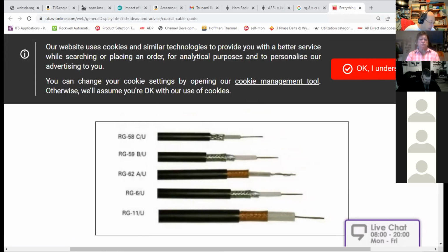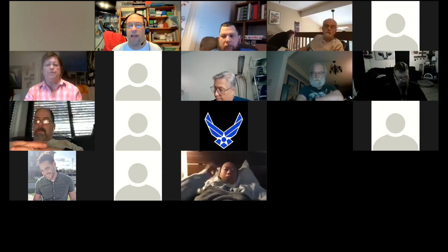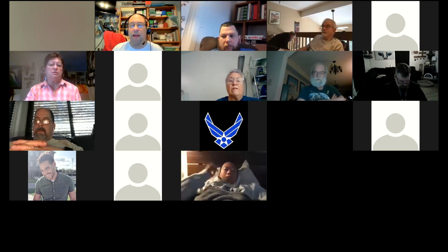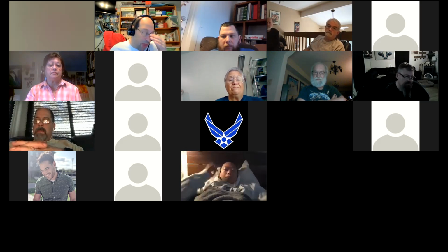Is the CU on that for copper? The CU and the B, there's AU, BU, CU, and that's kind of a definition of what the shielding looks like. Some cables are going to be single shielded, some are going to be braid plus braid plus an aluminum shield. Another thing is that when you buy a piece of cable, it'll say 99% tinned braid or tinned copper shield.